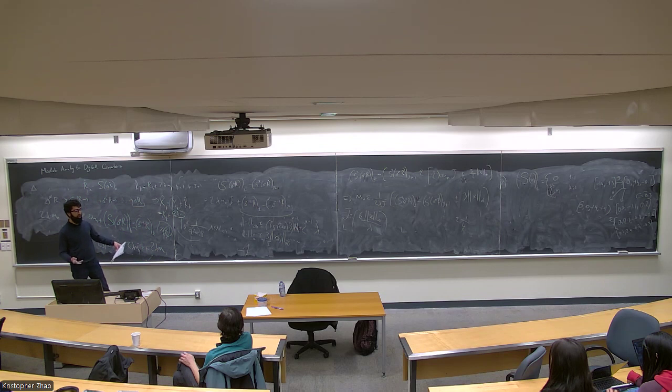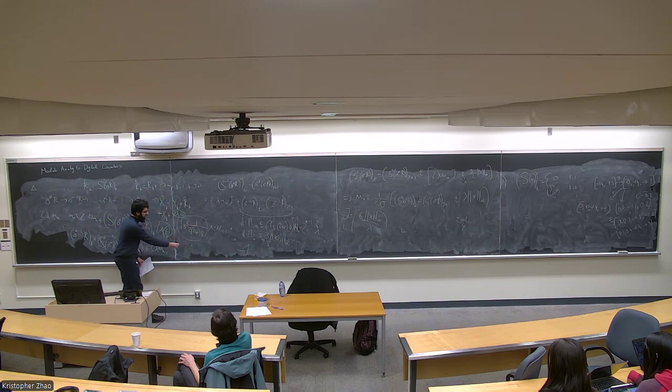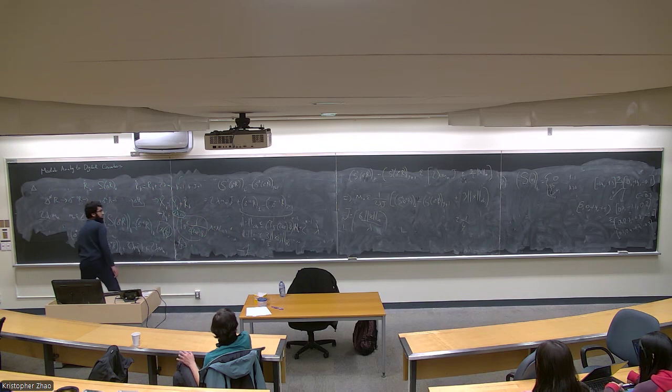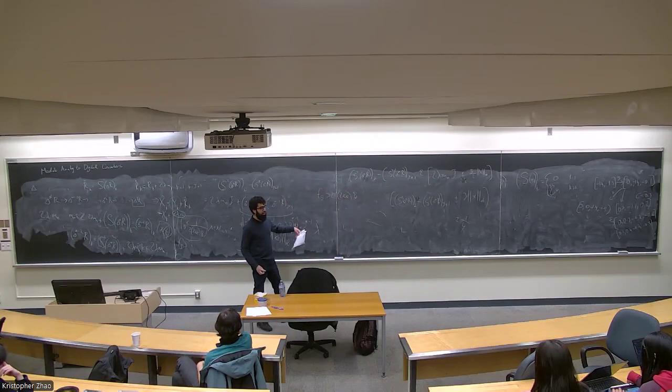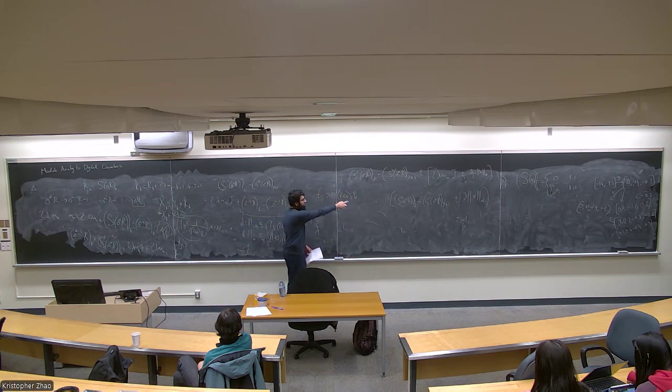In terms of the additional conditions that we require, the only new thing is this bound over here, which if you invert both sides, is equivalent to fs being more than... Let me just write it. So the only additional information that you need is that your sampling rate is bigger than 2 times 2 pi e times bandwidth. If you recall, in the Shannon theorem, all you had was 2 times B. Here we have this additional factor in the middle of 2 pi e.